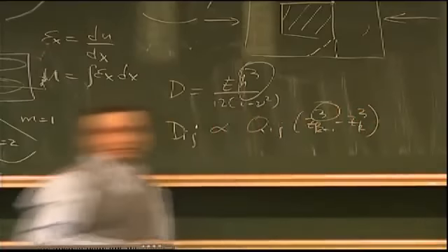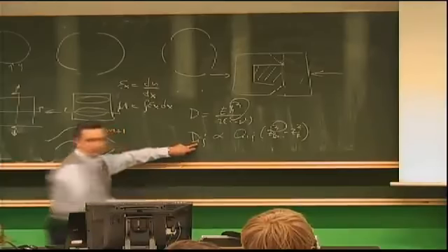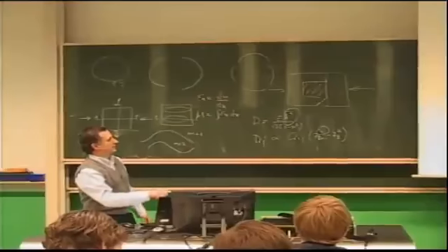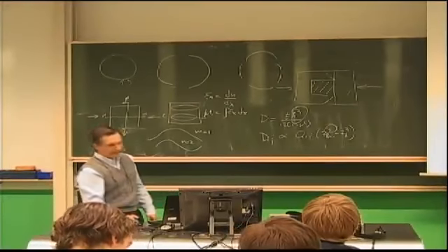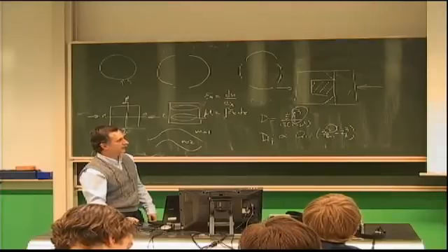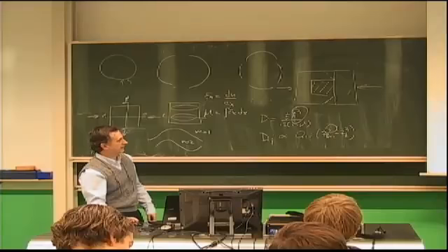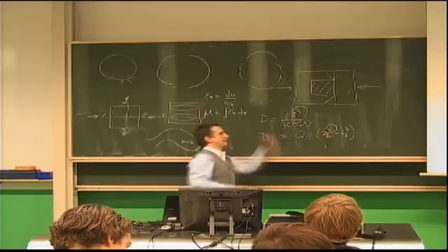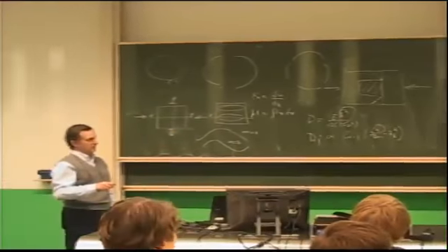Now this cubed means that because my buckling load is proportional to the D matrix, remember at the bottom here it's proportional to the D, I need to increase my D by that 1.2 factor, but because it goes like thickness cubed, then I bring it over to the other side and it becomes 1/3. So that's the 1/3, and therefore that's my 6.3%.